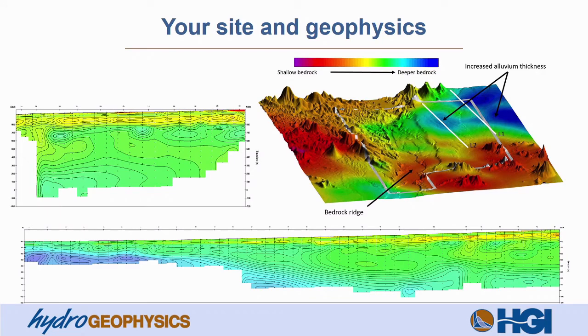One example of this work is the partnership of electromagnetic surface properties as identified by AMT modeling, with bedrock highs and lows as identified by gravity modeling. On the top right is a three-dimensional plan view of gravity data collected over a field site, where blue areas are increased alluvial thickness and red areas indicate decreased alluvial thickness, and thus bedrock that's closer to the surface. On the left and bottom, two AMT depth sections show modeled resistivity values at depth. Surface distance is shown on the x-axis and depth on the y-axis.